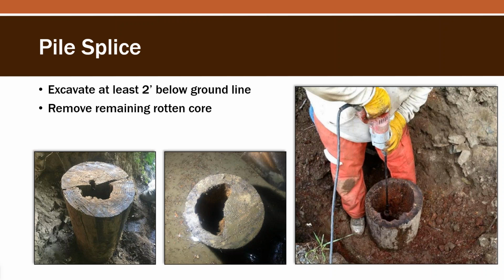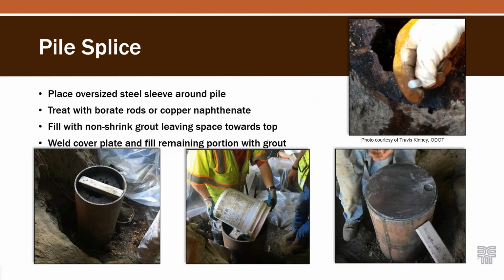You always want to get all the rotted material out. We did some destructive testing with Oregon State University on these repairs. And part of the idea was, do I have to dig until I get to 100% solid wood? Or can I use that 2-inch shell or so and fill in the cavity with concrete? And the destructive testing gave us confidence to be able to do what I've heard referred to as the cavity repair, where you fill the cavity as part of the work, and it just helps limit the amount of excavation you have to do.